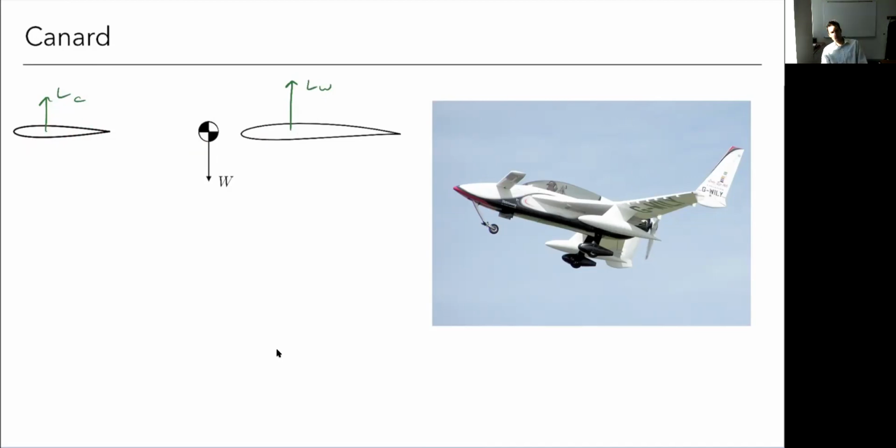But because I need the canard to stall first, that generally means I need the main wing to be a bit bigger to give me the CLs that I want. And so the benefits we said about the canard, that I don't need as much lift because the canard's carrying it, and the wing can be smaller, are mostly counteracted because the wake of the canard interferes with the wing, so I need more lift. And because of the stall characteristics, I actually need to keep that wing pretty big. So in the end, it's a tricky design. There can be cases where it can be good, but it's not the obvious win that it appears. And in fact, in many cases, it can be much worse.